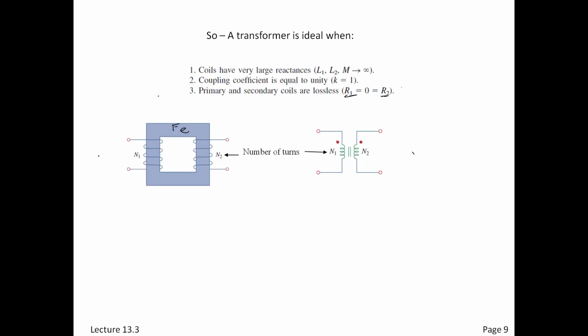This is often stated, sometimes just as a voltage ratio, voltage out versus voltage in, and from that you find the turns ratio. So you don't know the literal number of turns unless you do a little more measurement and exploration. Typically, this double bar in the middle is an indication that you have an iron core. It's not an exclusive indicator, but it's very commonly used, and it means high coupling. Pretty much it means iron.